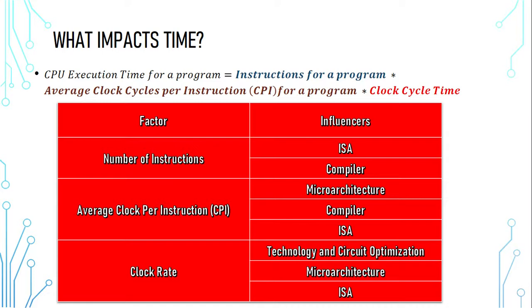For example, consider a processor with a sign instruction in its ISA and another one without this instruction in its ISA. If a programmer in his Python program does some sign calculations, after compiling the program for the processors, the first one will use a single instruction from its ISA, but the second one should execute many arithmetic instructions, usually generated by its compiler, to do that computation. So different compilers can lead to different instruction sequences with different numbers of instructions based on their optimizations.